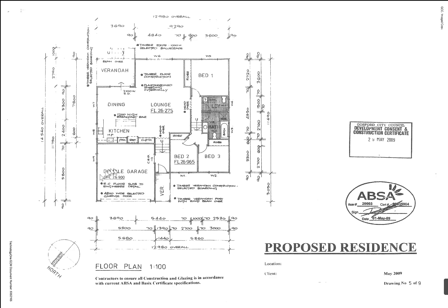Say, for example, here in the garage, we've got 26.9, which was down from that 28.72 benchmark. And then we would walk through a cavity sliding door, CSD, cavity sliding door. It's one of those doors that slides into the wall frame. We come into our front entry. We're actually going down the stairs here onto the main lounge area. Lounge, kitchen, dining, bedrooms and all those other rooms are 625 millimetres lower here than the garage. So we've gone through the door, down the stairs, into this area.